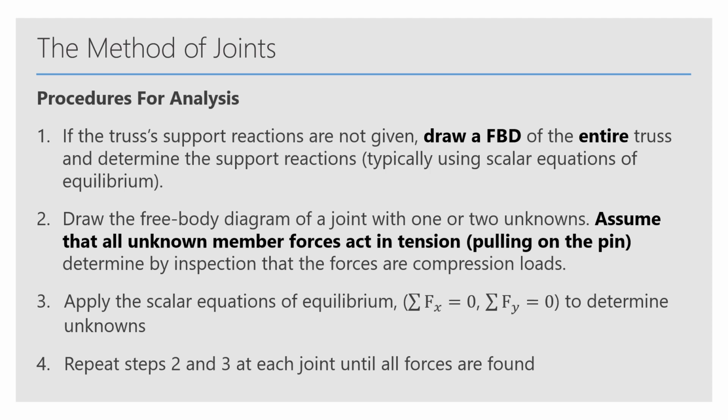Apply the scalar equations of equilibrium. We know these equilibrium equations. And then you want to repeat the drawing of the joint free body diagram and the equilibrium equations for each and every joint in the system until you solve for all the unknown members of the system.